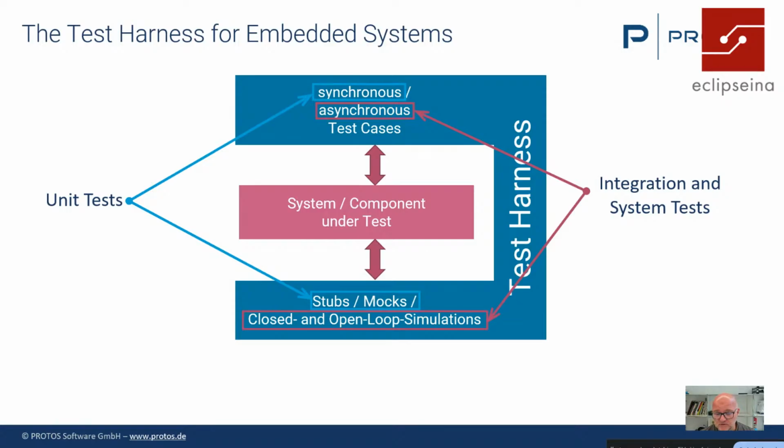That's very important, because if you just play back recorded signals, for example for a motor, your controller will not work. It will immediately go to an infinite level up, or it will go to zero. Because the motor needs to follow in order for the closed loop to work. And that makes asynchronous tests much more complex, or at least more complex. So that's what you need.